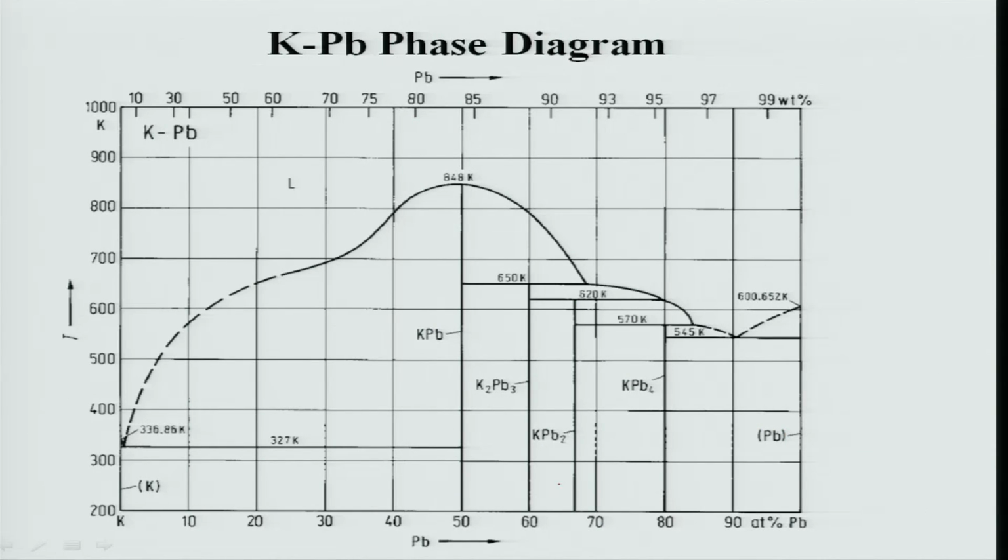This is the potassium lead system. There is a compound here, I guess, yeah, K2Pb3, forming by a syntectic reaction, again here L1 plus L2 giving rise to this.